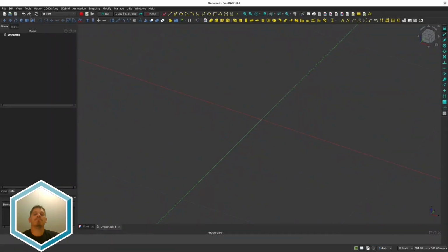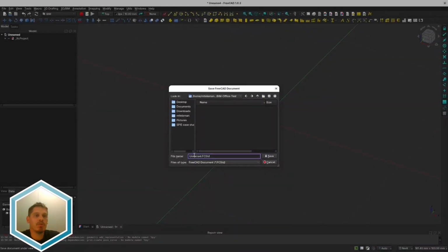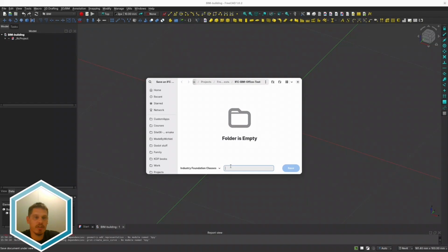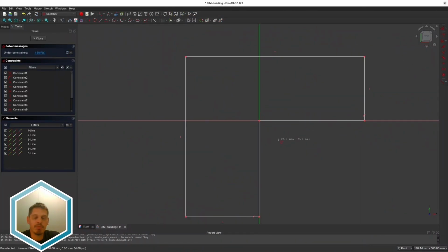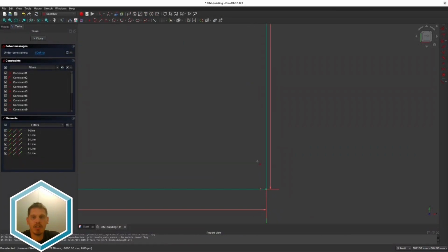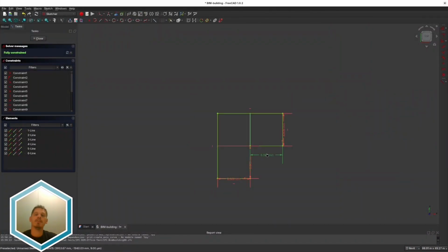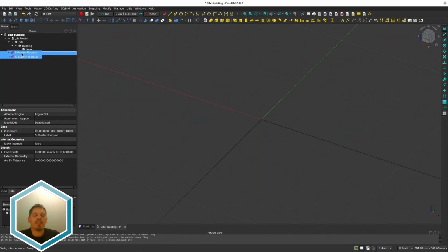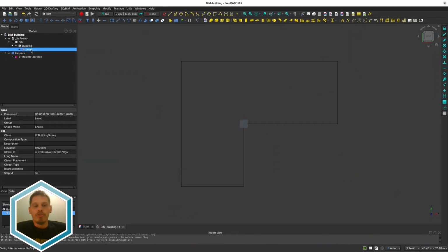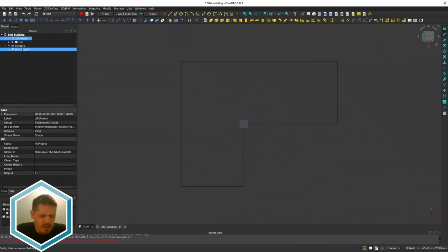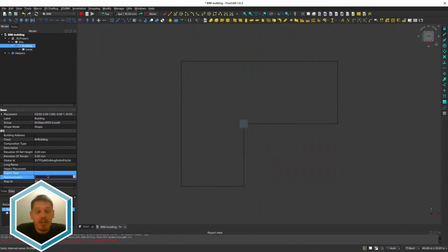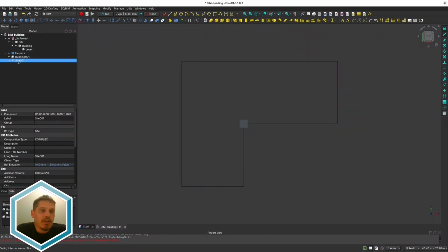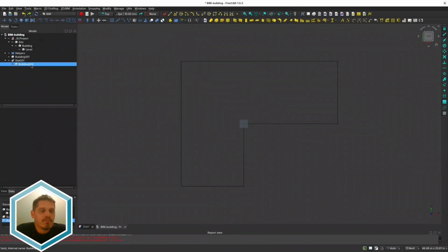So here I'm opening FreeCAD, I'm going to the architecture/BIM workspace, and I created an IFC project, and I'm creating a sketch to lay out a master sketch basically that will hold the level, the ground plane, the ground floor.